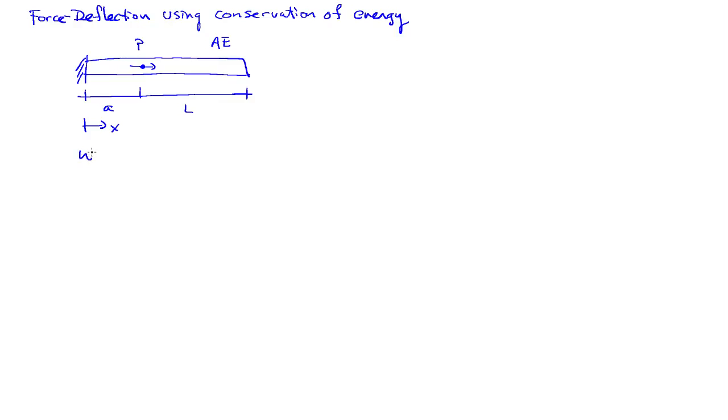So it's a linear elastic system, so the work in is 1/2 P times the motion I'm interested in, delta. And the work stored is the elastic strain energy. And we have two options. We can write it in terms of kinematic quantities, or equivalently, we can write it in terms of kinetic quantities or forces. So 1/2 r squared, the internal force, over AE dx.